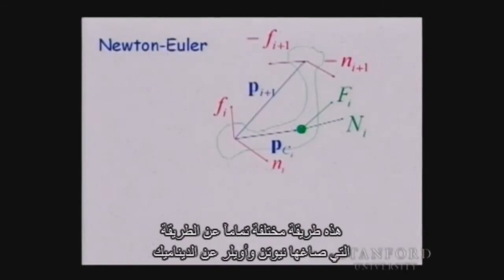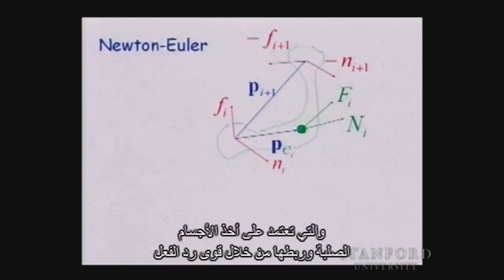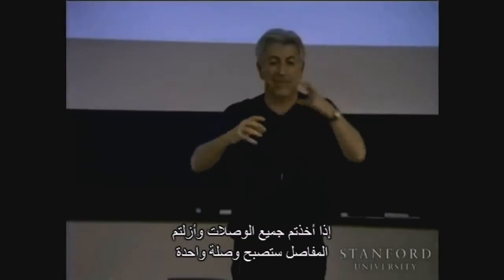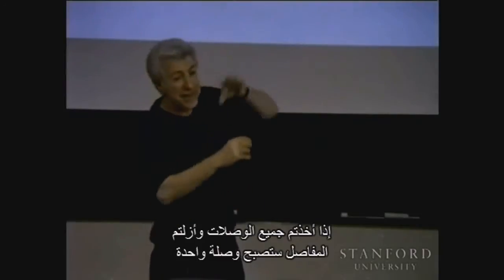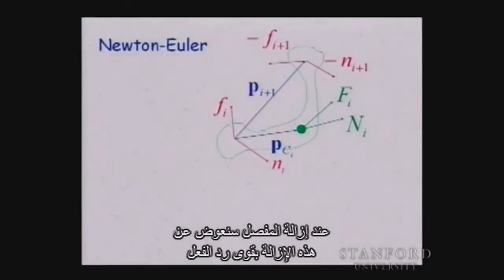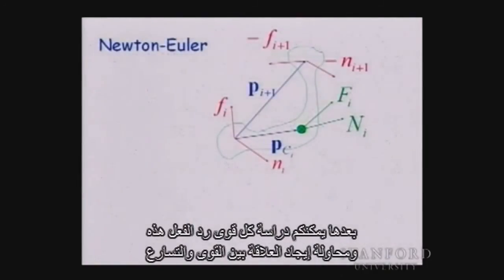So that is a very different way than the way Newton and Euler formalize the dynamics, which relies on the fact that we take each of these rigid bodies and connect them through reaction forces. So if you take all the links and remove the joints, you get one link, but when you remove the joint, you substitute the removal of the joint with reaction forces, and then you can study all these reaction forces and try to find the relationship between forces and acceleration.